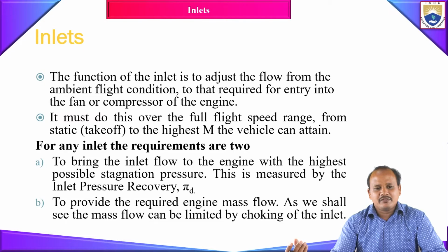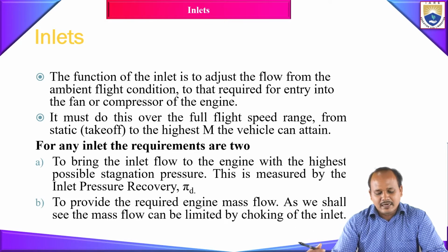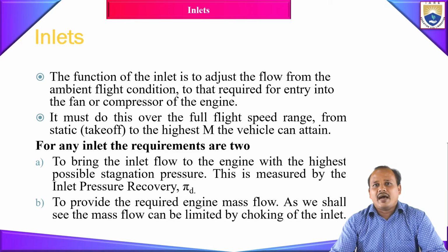If I keep some solid object in the incoming flow field, it is going to produce a certain amount of loss. Similarly here, since the intake is made of a solid wall, when the flow is passing through this intake, there is going to be a certain amount of loss. So the first and foremost requirement of your intake when we start designing is that it should have the least amount of total pressure loss.